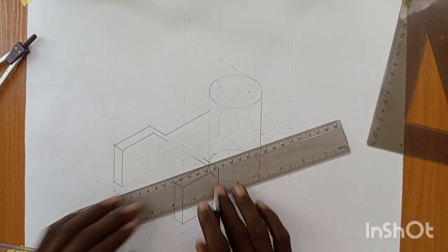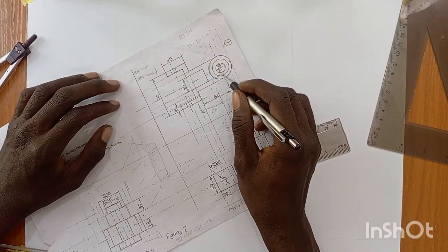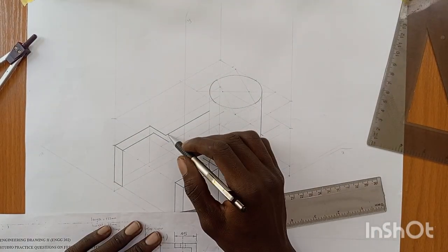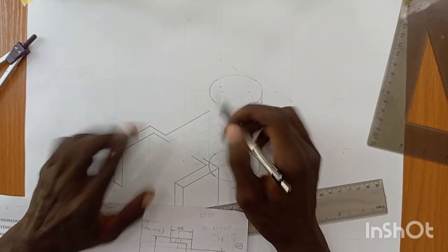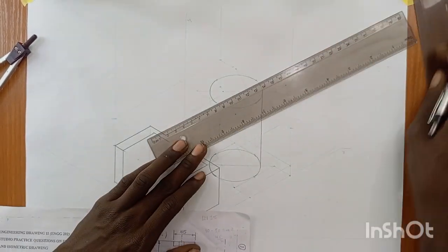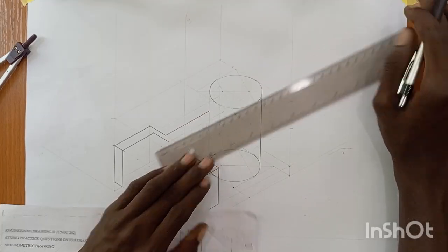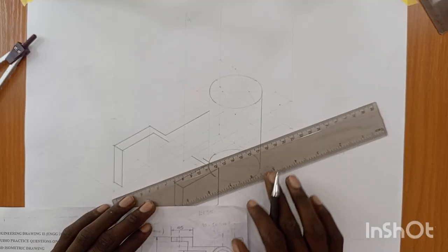Center of the cylinder. Ideally, as you can see from here, the length from this 45 points here to the center of the cylinder is given as 65. So I'm going to measure 65 from here inward, and from here inward. But since the cylinder is covering the other part of 65, draw the line anyway it touches the cylinder, you stop there. Because you see that this line is not up to 65, right? It's not up to 65. Because the line touches the cylinder from the back, and the cylinder is covering it, therefore it cannot be seen.